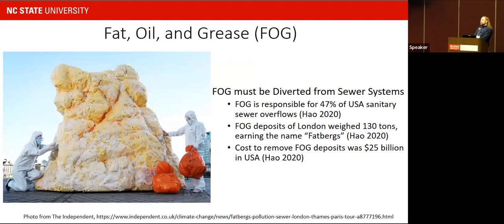This is a waste stream primarily associated with cooking. So after you render grease out of a piece of meat or have some oil and you pour it down the drain, it finds its way into the sewer system, where it coats sewer walls and saponifies, that is, it coats and hardens on the pipe walls, restricting flow. This accumulation of layer over layer can ultimately block flow altogether. And with nowhere else to go, sewage ends up in places that we don't want it, i.e. overflowing in an event called the sanitary sewer overflow.